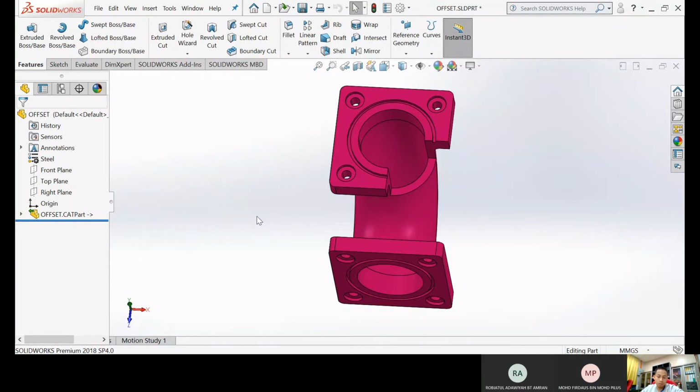Okay, for part 9, with the surfaces, in this part, we can create some geometry that will fill the entire pocket. And then all the unnecessary surfaces need to be trimmed so that the funky geometry will not appear. The ruled surface option can be used to produce a sweep going toward a plane.